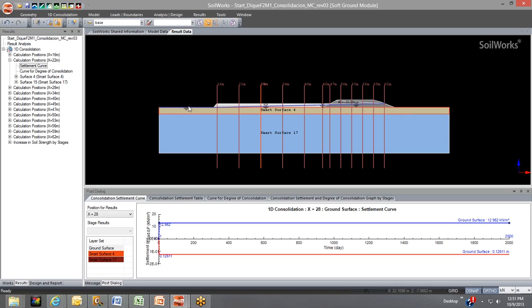But for example, if I were to model a change in the weight, or if I were to do a construction stage analysis where the embankment is slowly being built, obviously this would increase with time. But since these embankments are just there, nothing really changes. All of this is very straightforward. So it's just straight. And this red line here goes over your displacement or your settlement.